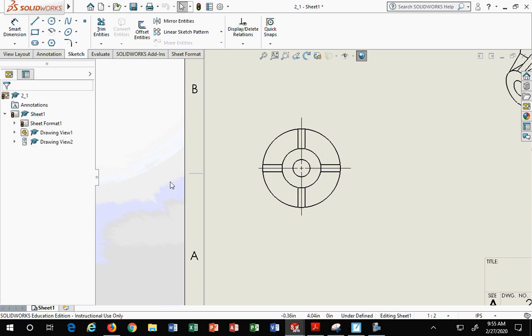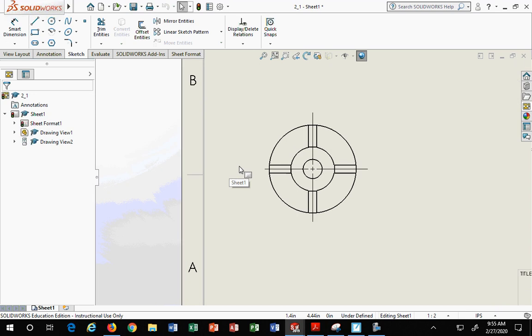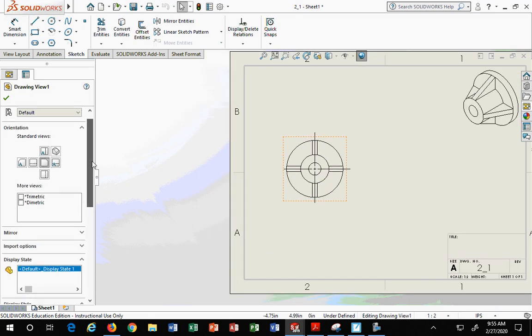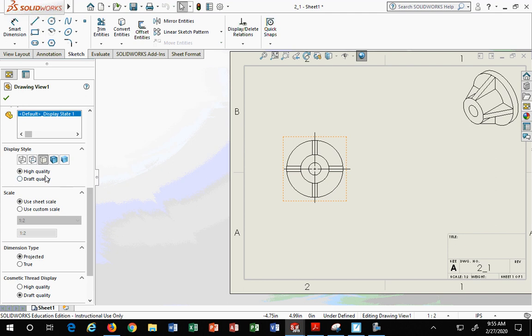Which for detailed drawings is essential. Those of us who are builders must see the hidden lines. The out-of-the-box default in Solidworks is hidden lines removed. You must turn this on. You need to see hidden lines. Hidden lines visible should be the default setting in every single CAD product, for anyone listening to this video.